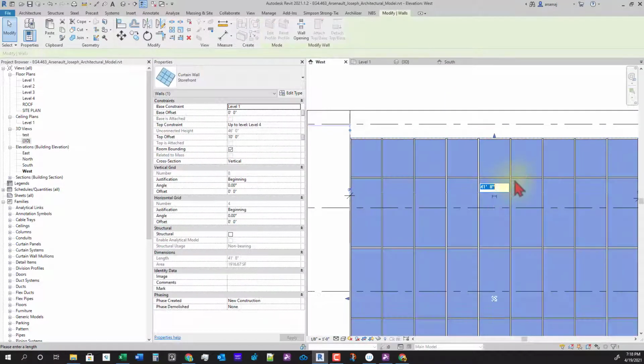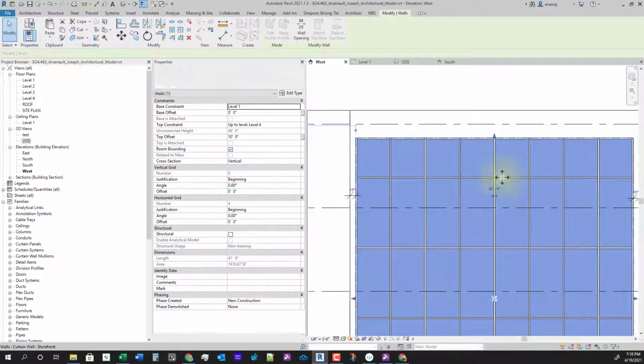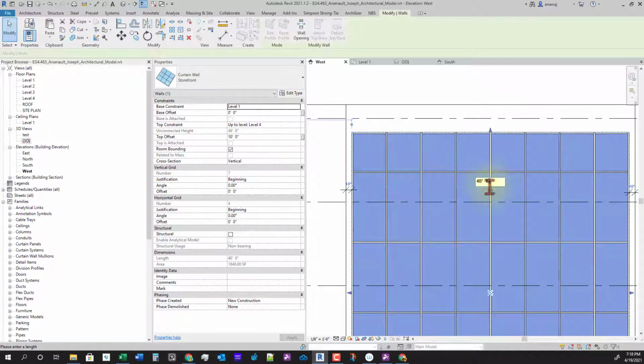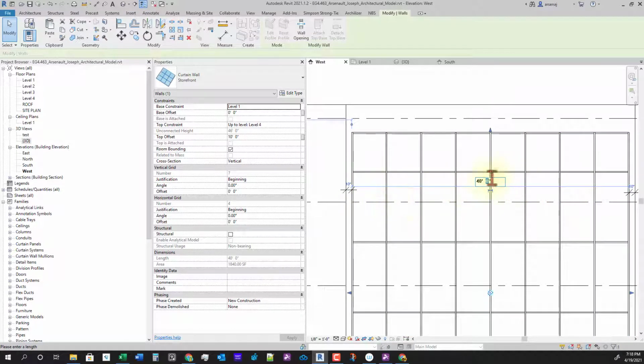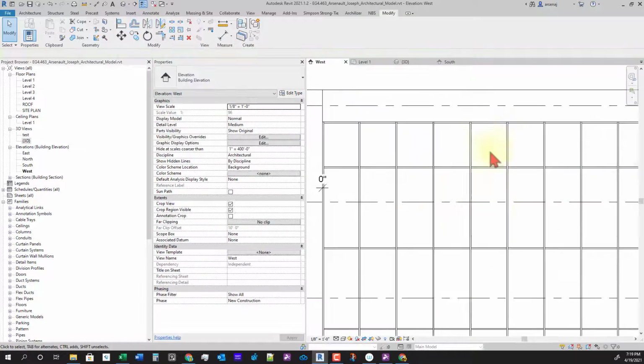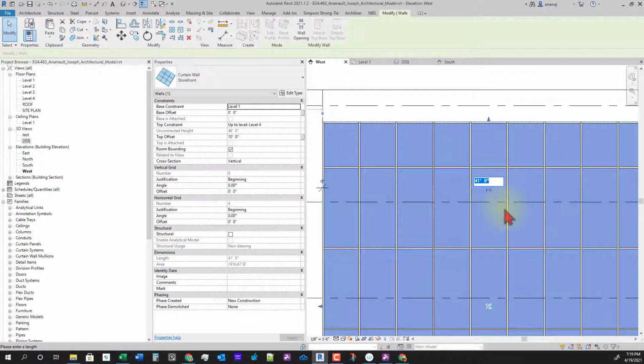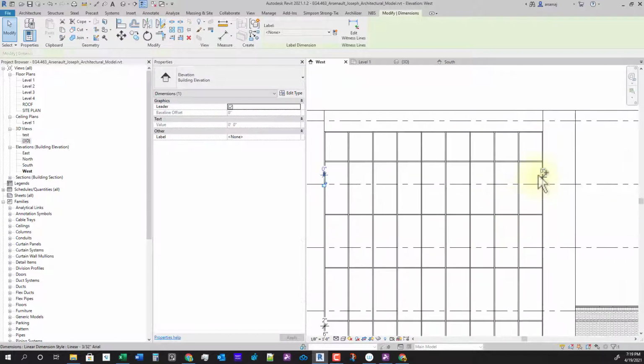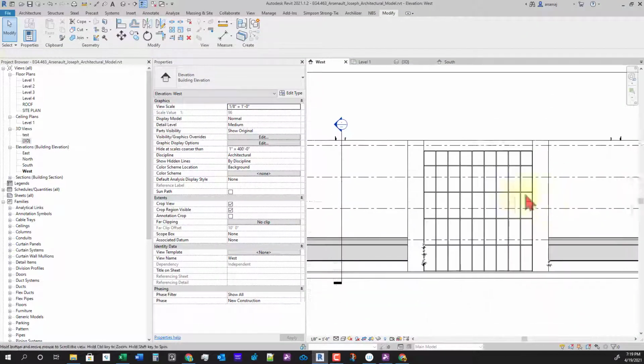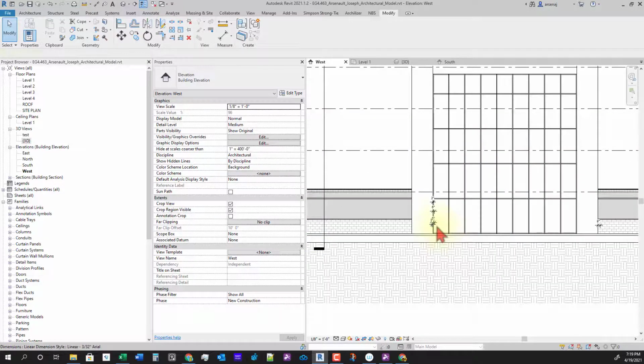So what I did was I did 40 feet is what we originally had. And so instead of doing the math and figuring out what 10 inches and 10 inches is 20, and then, well, 20 inches minus 12 and whatever's left over, making it 41, and whatever the change is, you can just add 40 foot 20 inches to your Revit temporary dimension, and it's smart enough to know it's 41 foot 8. So now we've got our